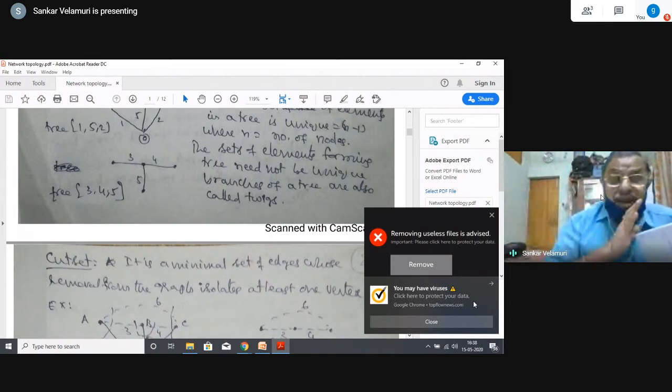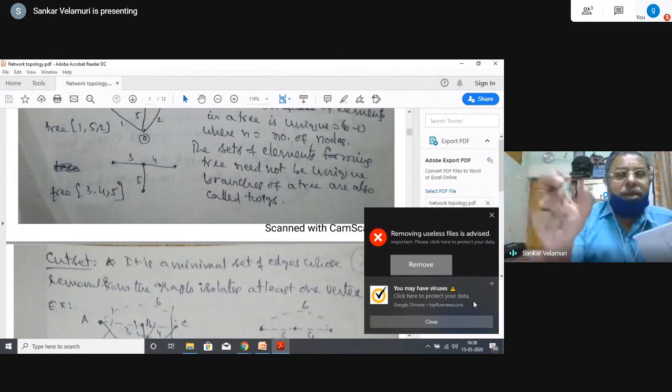One person has asked why graph theory is chosen as a method. No, I have not stated that it is a method. It only gives an idea about how many equations are required to solve the problem using the loop current method. That is the number of links. Although there are 8 elements in the network, I need only 3 independent equations. And I need only 3 nodal voltage equations for nodal analysis.